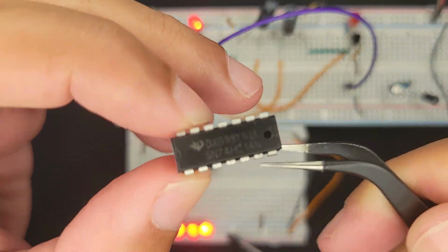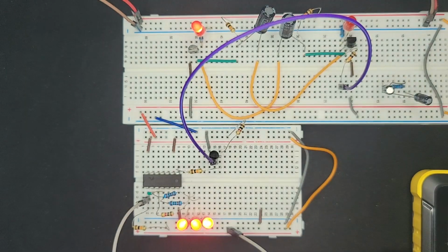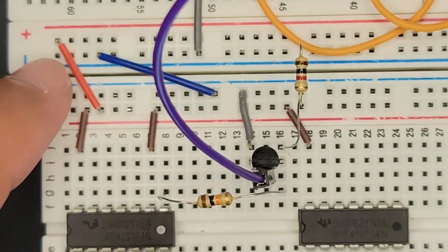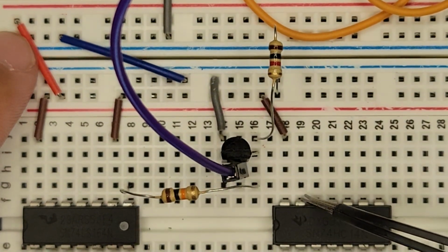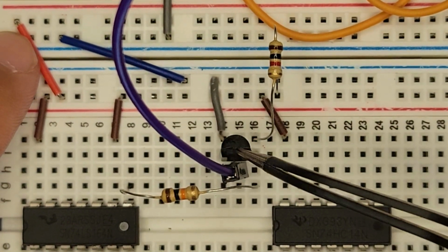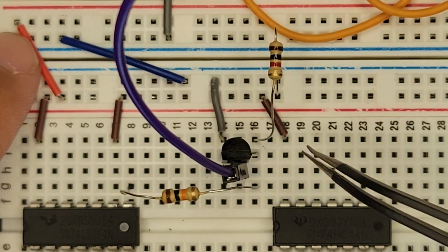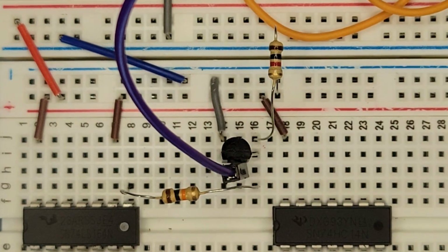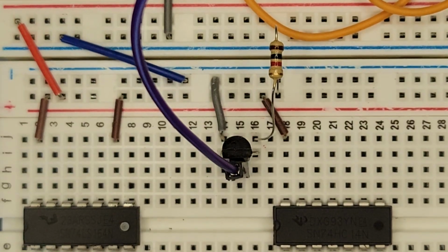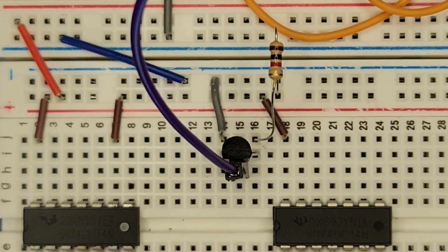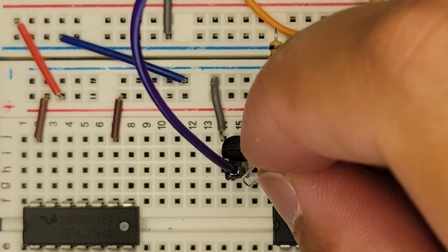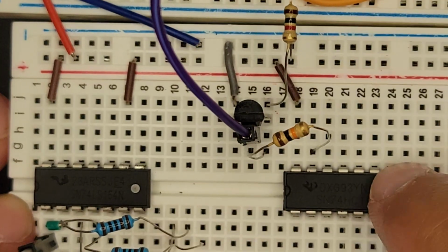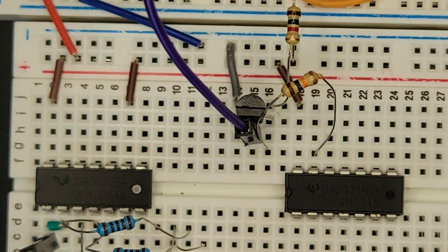All right, this looks like the HC14. So I'm going to plug in power. I'm going to give my little home right here. And then pretty much all we have to do is on the second pin, we're going to have the output of our amplifier. Although I don't know if we need the amplifier anymore, but I'll just keep using it. And then the output will be this one, which will be our new clock. So the output of this little inverter amplifier that we have will go right into pin 2, just like that. And then the output should be able to go straight over there.